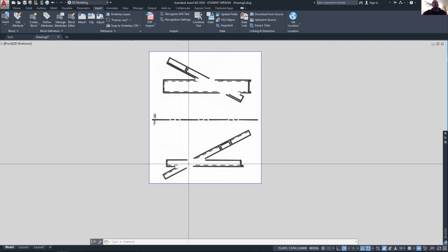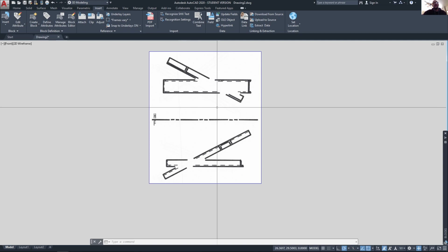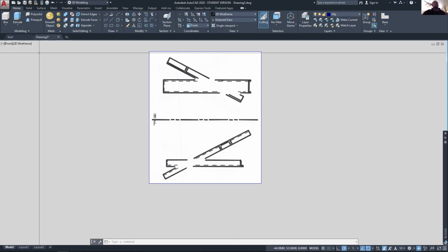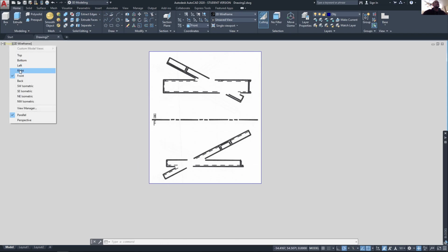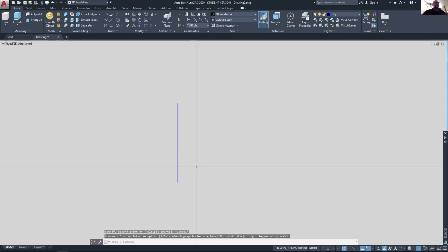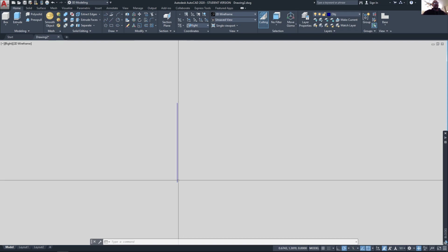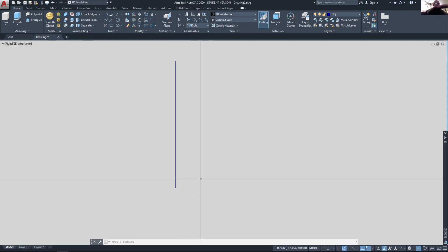We have several assignments in which you need to do that. I want to extend this a little bit further by drawing these two pieces in 3D and kind of placing them in 3D, because I do have their coordinates here I can use for them. So taking some measurements, I'm going to go to my right side view. I'm going to draw the L channel and the C channel. So let's take a right side view. And there it is. And I'm going to go ahead and place them just behind the frontal plane, but I'll measure that and get them in the right place later.